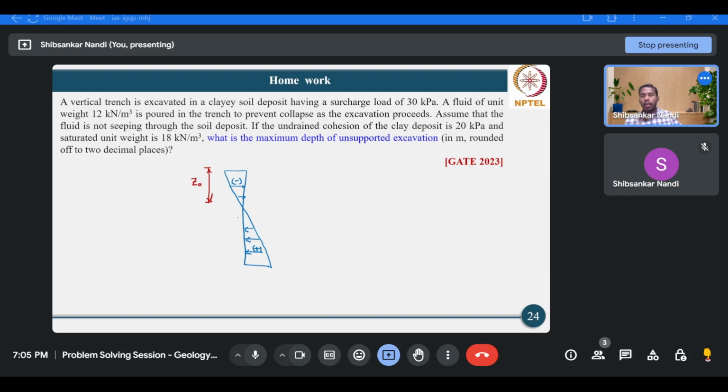Now, if we take the resultant of this distribution, for the top Z0 portion it's negative, it's tension, and for the lower Z0 it's positive, it's compression. So they basically nullify or cancel out each other. As a consequence, the resultant thrust, the resultant PA, is basically 0.